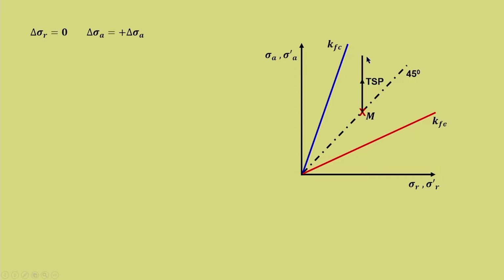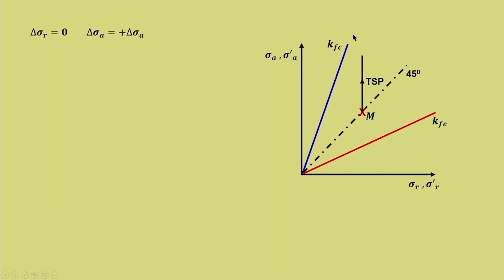In fact, when it comes to undrained testing, you will see that the total stress path will not represent what it actually has to represent about failure. So, it is all governed by the effective stress path. So, whether it is complete or not, whether the total stress path is meeting or crossing the failure line, it hardly matters.